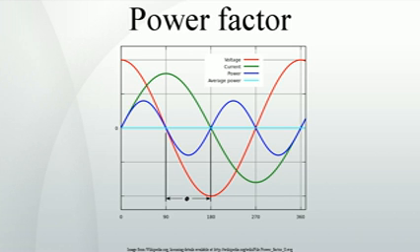At unity power factor, the current in A is in phase with the circuit current, and coil A provides maximum torque, driving the instrument pointer toward the 1.0 mark on the scale. At zero power factor, the current in coil B is in phase with circuit current, and coil B provides torque to drive the pointer towards zero. At intermediate values of power factor, the torques provided by the two coils add and the pointer takes up intermediate positions.